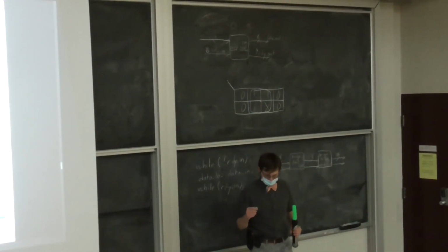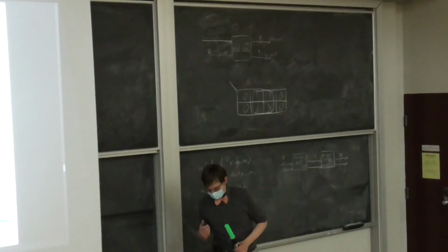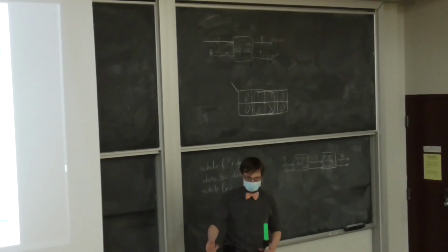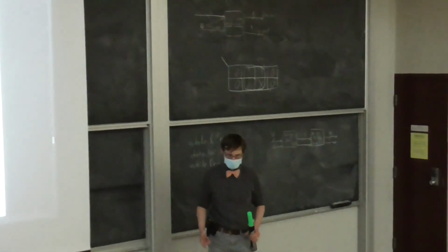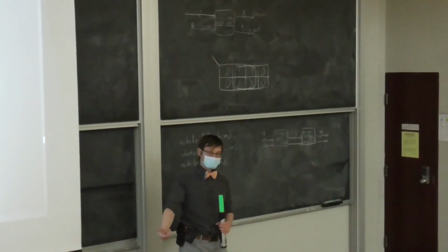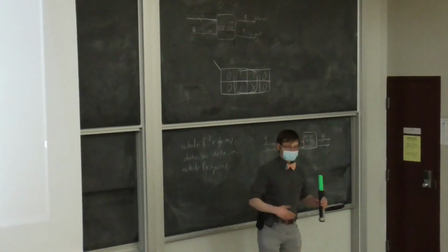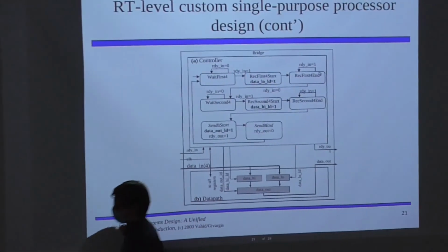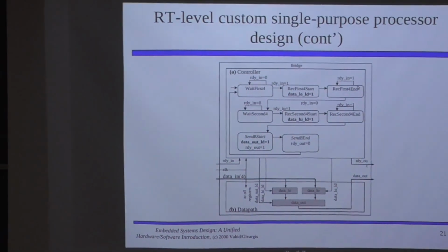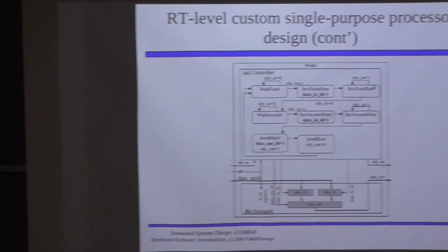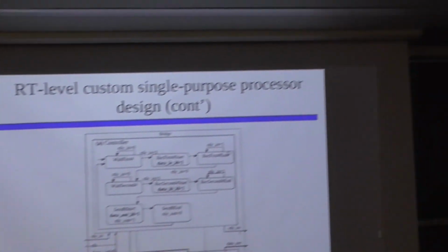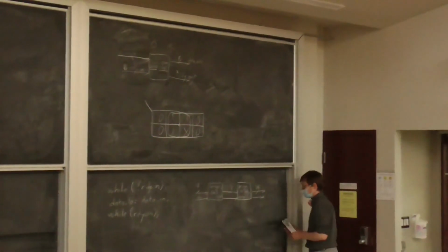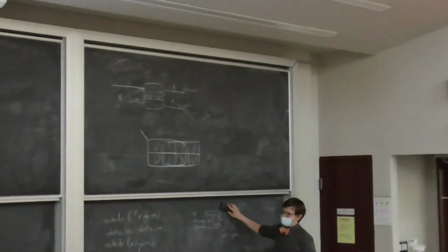It's like a politeness thing. It's like shaking hands. I receive data in this manner, I will pass it on in the same manner. That way everybody's happy. If a designer is making design decisions based on that type of an interface, not including the ready out signal would be a huge violation.